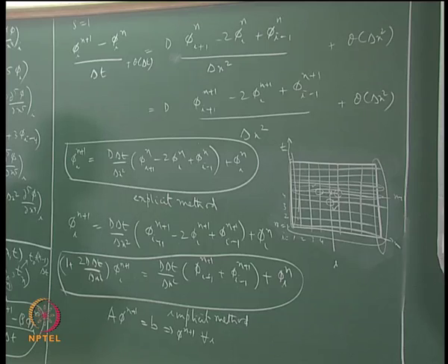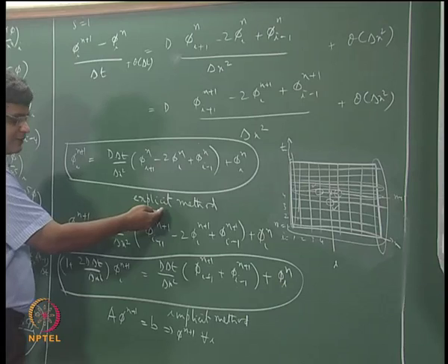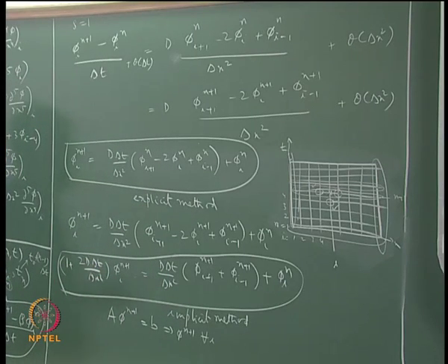We are anticipating what we will be discussing in future classes. From that point of view, the choice of whether we choose the explicit method or the implicit method is not as clear cut. Sometimes we may be forced to use an explicit method because it is so simple to program. But sometimes we may find that it severely restricts the delta t values that we can choose, and in such a case an implicit method will guarantee us a solution.